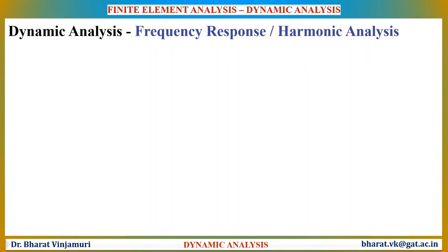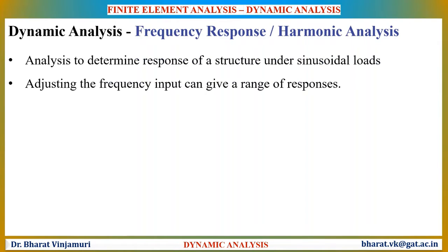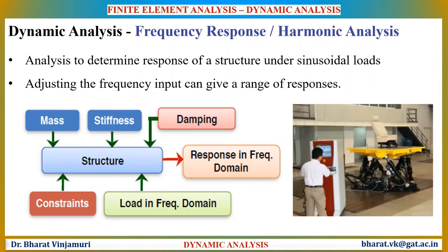Another type of dynamic analysis is frequency response or harmonic analysis. In this analysis, the response of a structure is determined under sinusoidal loads. That is, the loads will be periodically applied and the frequency of loads will be studied on the structure. The response of the structure due to these loads is studied to determine the effect of vibrations.